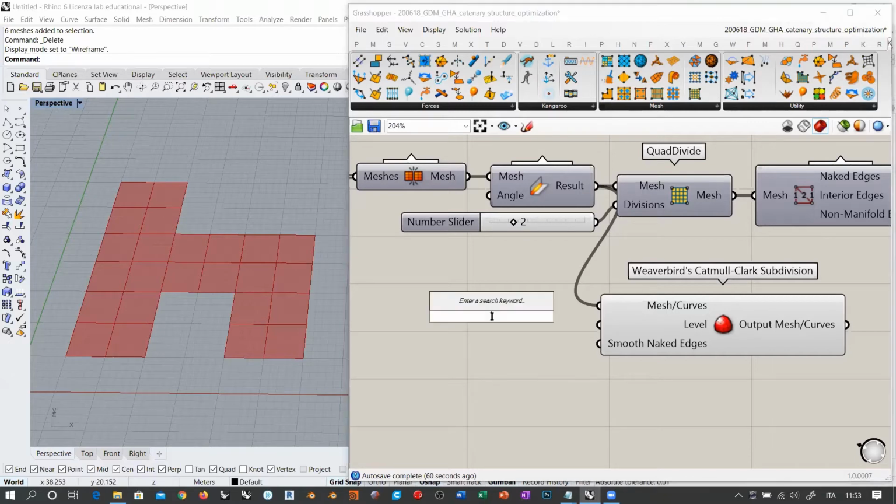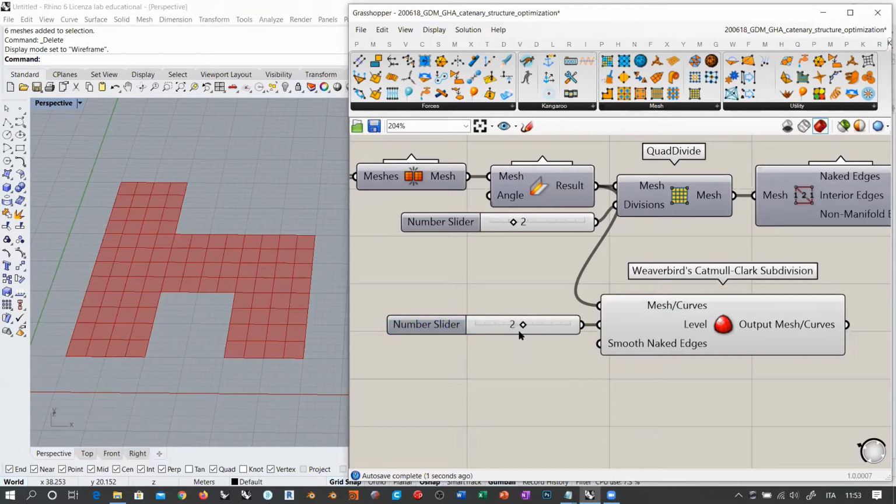Okay, so if I set this level with a slider between 1, 2, 3, it doesn't allow more than 3 repetitions because of the number of faces that you will create. So you see that with 2, you get 4 by 4, and then there is 3, and you already are at 8 by 8. Okay, so you don't have this kind of direct control over the amount of polygons per side. Okay, this is a geometric progression basically.